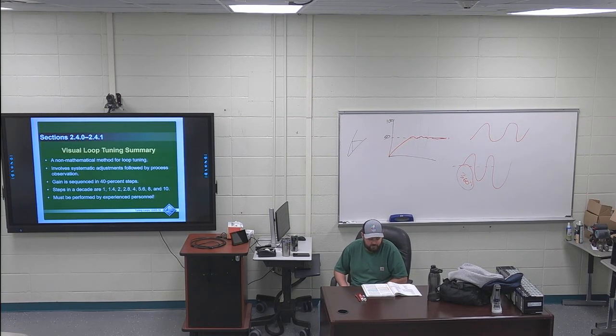So yeah, if you change something 40% of your gain, I guess that isn't a ton, but I know in that lab you go up by 20s. Your gain is going up by 20, so it's at least 50% you're going up by, and you'll notice how much faster that's going to open up that valve and try to get to that set point. So it's important that you change your gain incrementally, like not changing it from 1 to 50, change it from like 1 to 5 to 10, like increase it steadily, if you're trying to find a steady state with these PID controllers.